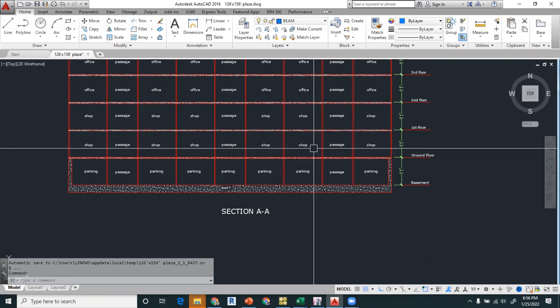If you go back to the slides, you have seen that normally the negative bending moment is more in beams and slabs. That's why we are using more reinforcement. But there was no need to give 3 layers at the top. For demonstration purposes, I have already explained that due to the lift pit, we are incapable of designing the actual lift pit in the raft.